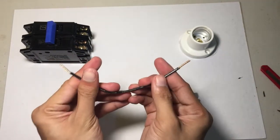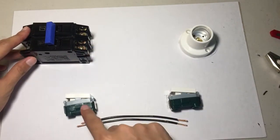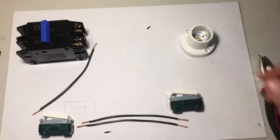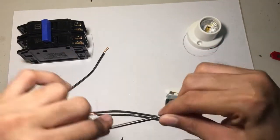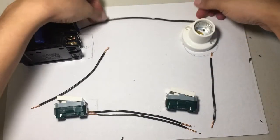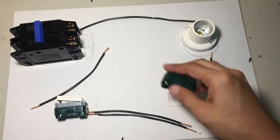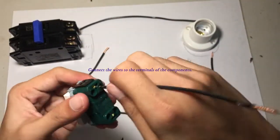For the two output terminals of the switches, we need two wires. Prepare the wires that will be used for connecting the circuit breaker to the switch, the bulb socket to the switch, and the circuit breaker to the bulb socket. Now all the wires are prepared, and we begin connecting these wires to the terminals of the components.